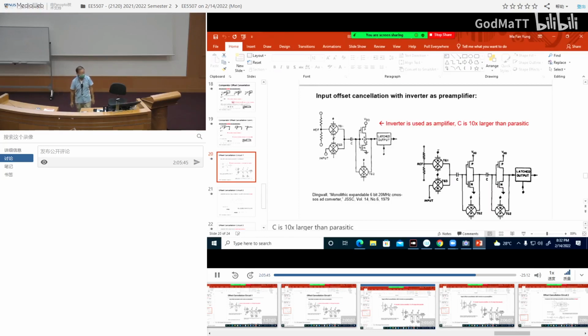And you may not understand why until you realize that actually in the capacitor there's a small piece of wire which actually is an inductance at very high frequency. So you can see. That's why it's interesting when you see this kind of schematic.